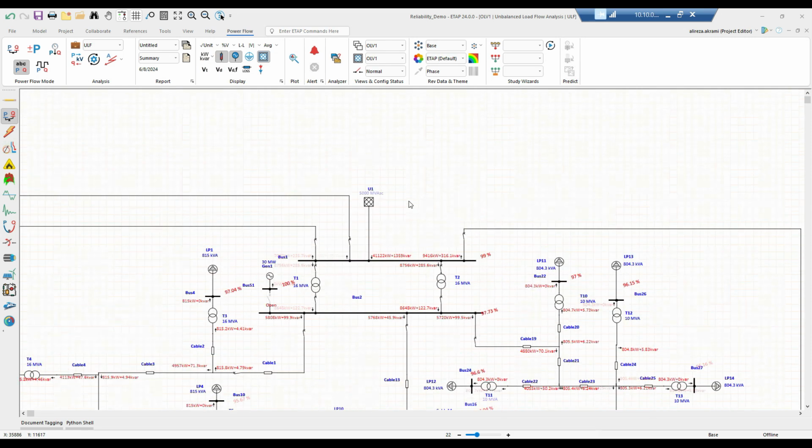Let's zoom in a bit here, and we can see that the amount of power that is supplied by this utility is about 41 megawatts. So if I'm using this DG as the backup generator for my system, then I should know that if the capacity of the DG is not as large as this value, then anything beyond that will be cut off in practice.